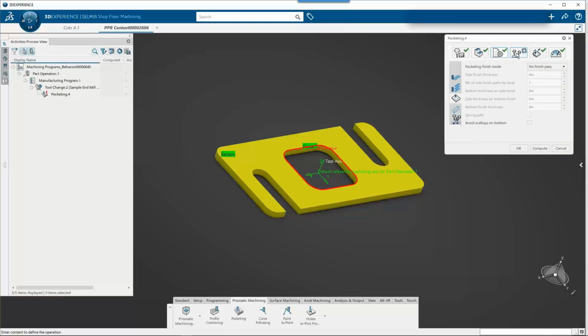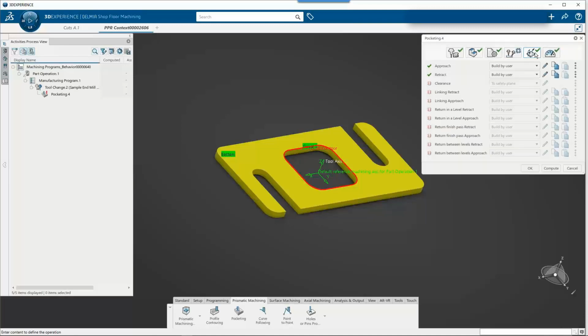We're not telling you how to program. We're just giving you the tools to make your life easier. Same with tool axis. If I had multiple axes or I had other roles from DELMIA, then I can turn on 3 to 5. When we program in 5-axis in DELMIA, it's simply turning on a 3 to 5. I don't have to reprogram the part. I can just leave it as 3, or I can make it 5, and then just define more geometry to make it that 5-axis toolpath.